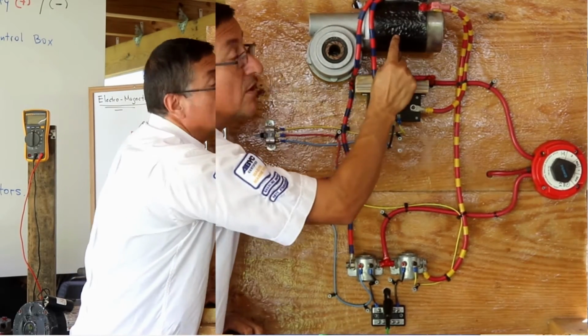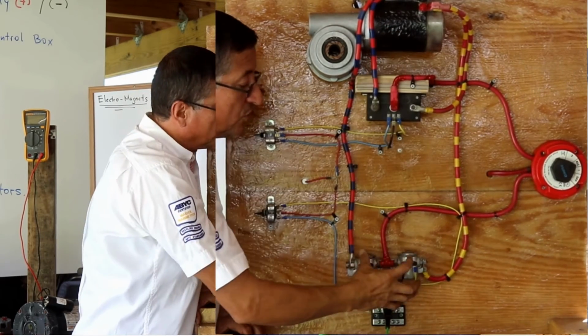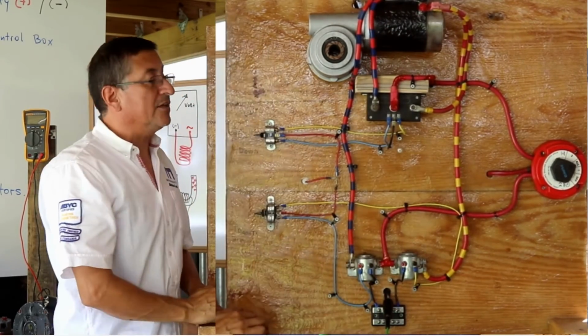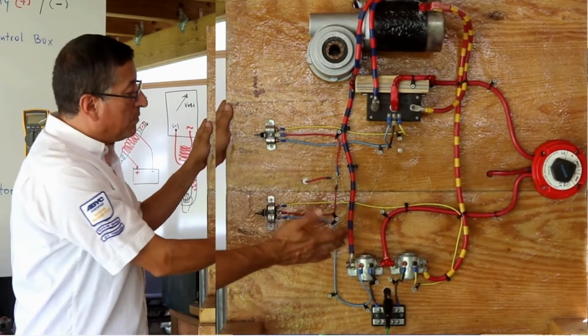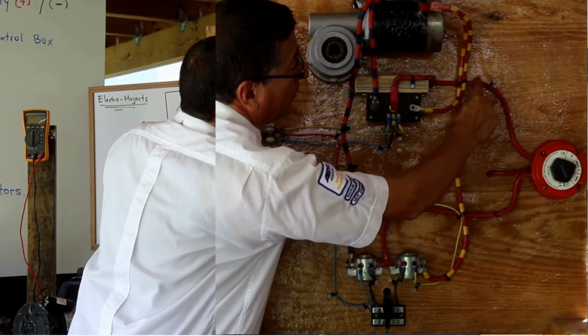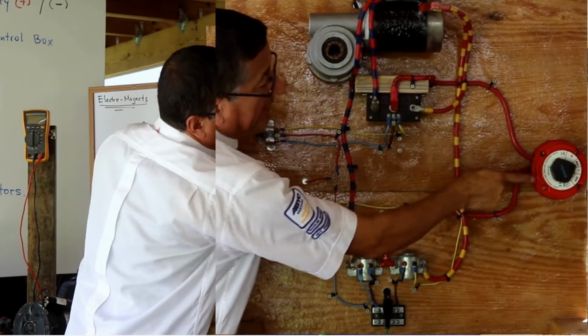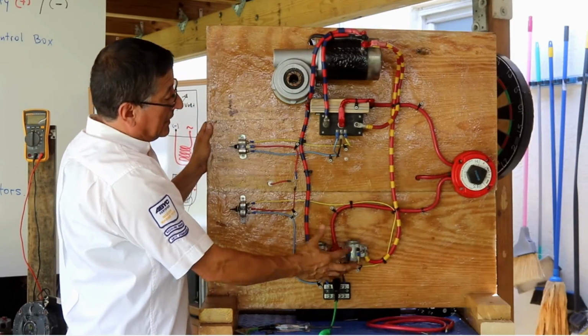What is the capacity of the motor? Depending on the capacity of the motor in amps, you need to choose the capacity of the relays, and you do the installation. In this particular case, I put both of them. I connect the switch selector. I have one output for one and output number 2 for the other situation.